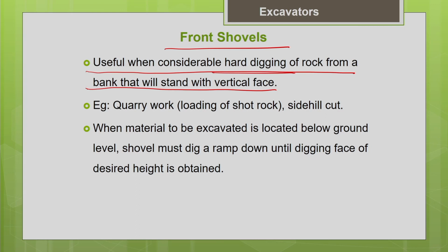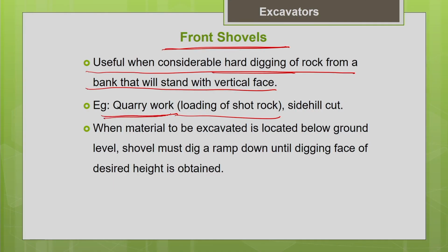It can be used to excavate any bank of material or in a quarry. Very commonly you can see this machine in a quarry. Whatever rock you have blasted using the blasting method, those blasted rock pieces, or shot rock, can be excavated with the help of the front shovel. So, it is used in quarry work for loading of shot rock. But it is purely dependent on a truck or any hauling machine for hauling the material. This shovel will swing its boom from loading to dumping position and dump the material into the truck. It is not designed for high mobility. So, it is used for quarry work or side hill cutting.